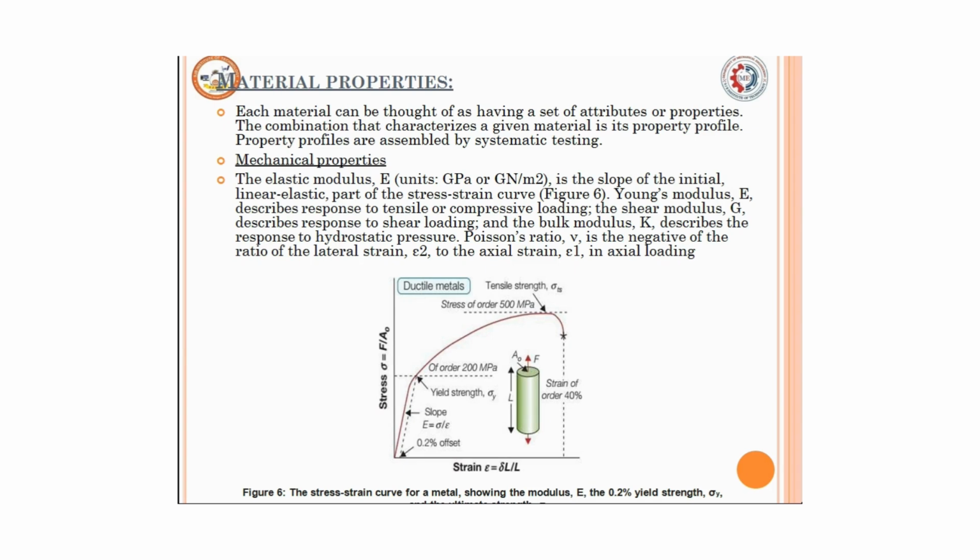for a material subjected to tensile or compressive loadings. Based on that, you'll be able to get the stress-strain curve, and if you consider the slope of the graph, then you'll be able to compute the Young's modulus. Here we can see the ductile behavior, how the material behaves when stress versus strain is plotted. So you can find out the Young's modulus. You can find out after what load the material will be elastic, or it is going to take ultimate load, or when it is going to fail.